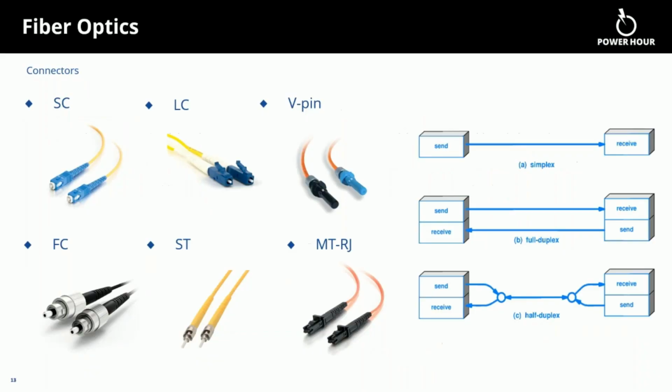So now that we've looked at the cables, we can look at the terminations. They're terminated with a variety of different connectors for different applications, density, or performance. For example, you'll see FC connectors utilize a metallic body and spring-loaded ferrules, which make them suited for high vibration applications. However, you will see slower speeds than LC connectors.